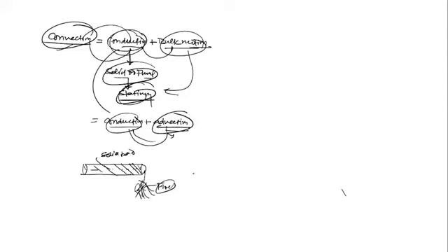What is the mechanism of conduction, I will discuss later on. I am just describing how the conduction works. The molecules are fixed at their position. There is no bulk motion possible. As we keep heating, the temperature at this side will be T1, here T2, here T3, here T4. Obviously T1 is more than T2, more than T3, more than T4. That causes the temperature gradient, and if it is the x direction, that gives dT upon dx. Yes or no? Temperature gradient, the temperature variation in the x direction.